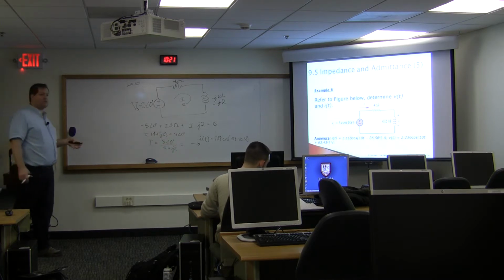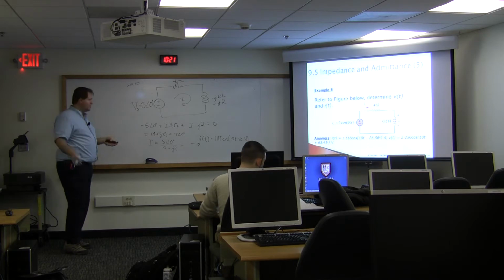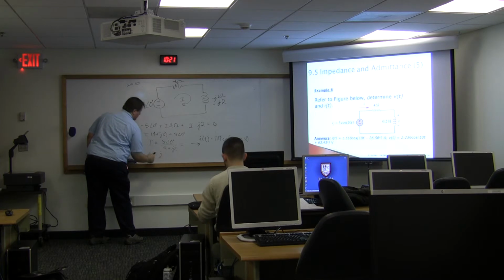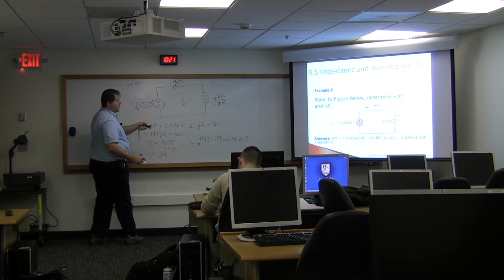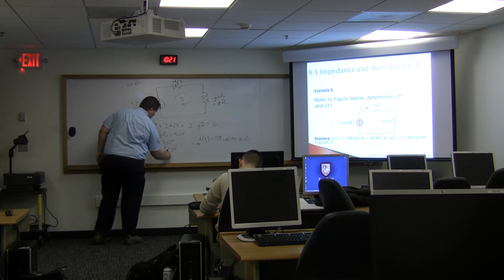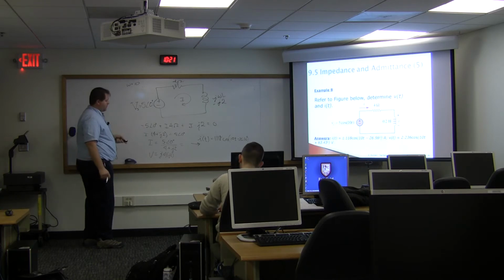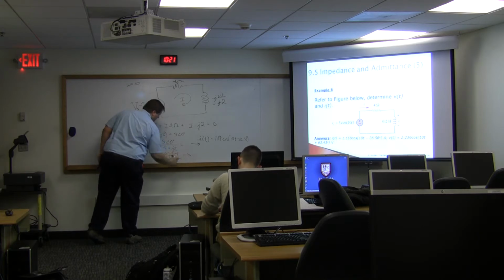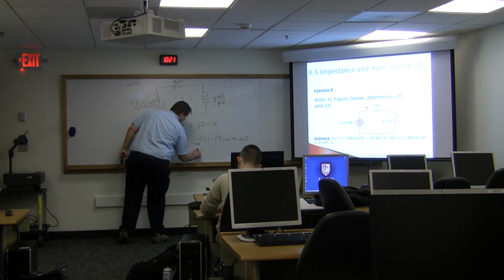And so what's the relationship between I and V? Well, V equals j omega L times I. So once I have this, I can just multiply. So the j times the 10 for omega times the L, right, which is the j2. That's what it's become in phasor form, j2, times this I right here, the big I. And then that I can transform into the V of t form, little v of t, right? Time dependent.